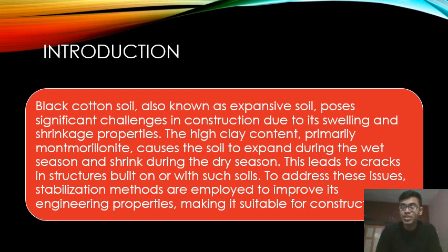Okay, so this leads to cracks in the structures built on or with this soil. If we construct anything over it, it has the tendency to crack during this process. So we need to address these issues. Stabilization methods are employed to improve these engineering properties, making it suitable for construction. This is the focus of this lecture, stabilization of black cotton soil.